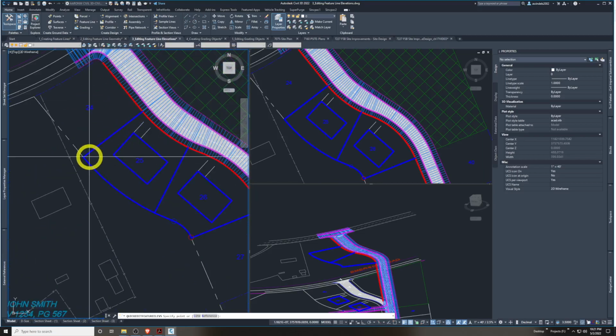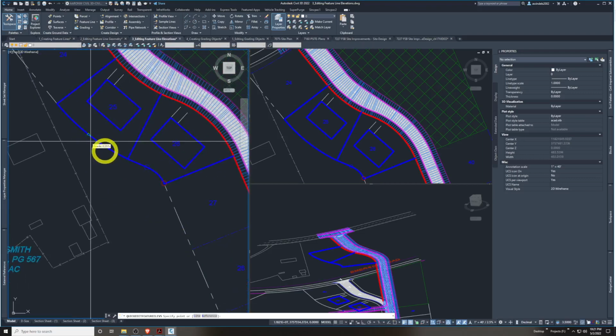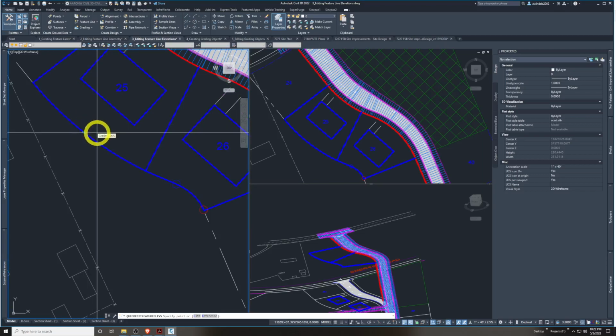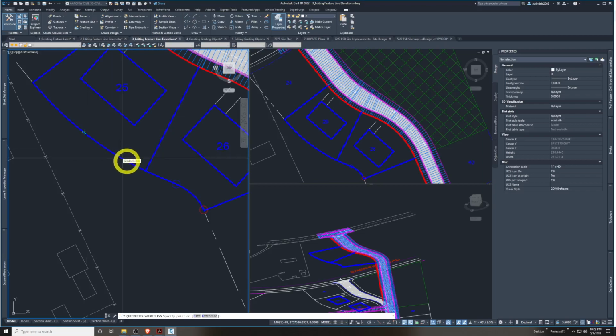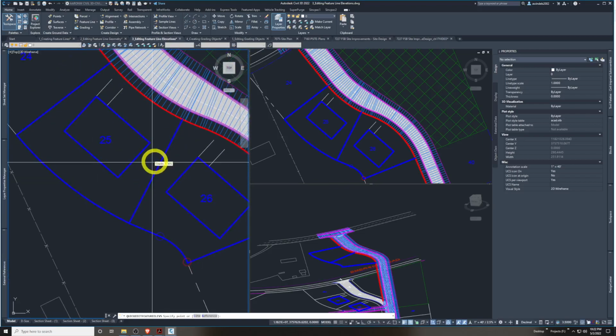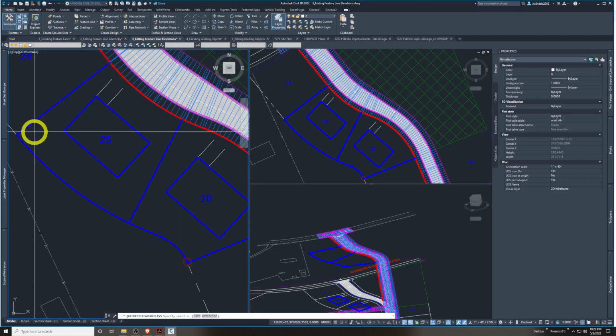Let's go to the other corners and just note the elevations. Let's hover on them. So this is 190.06. This one, the grade shoots down in a direction, barely. It's almost flat, almost less than 0.5%. It goes downhill this way, uphill this way, so always mind the direction of your grading arrow. Here's your elevation of 190.45. It's pretty flat. We go this way, and this is gray, like I said, because it's connected to the corridor feature line. So it goes downhill this way a little bit. So our high point is over here.